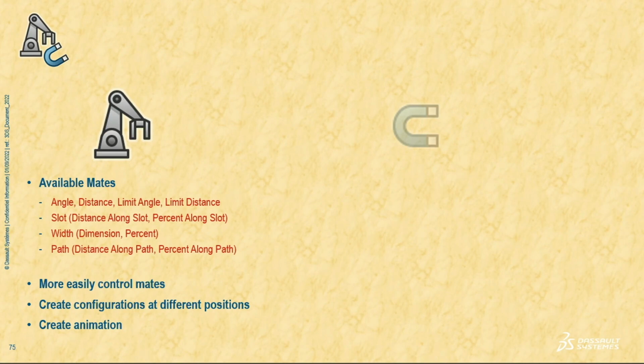Also, just like with that last section, we talked about sometimes seeing those angle mates flip, those different angle types, right? What's that option called? The reference entity, right? Good thing to define to help alleviate that.